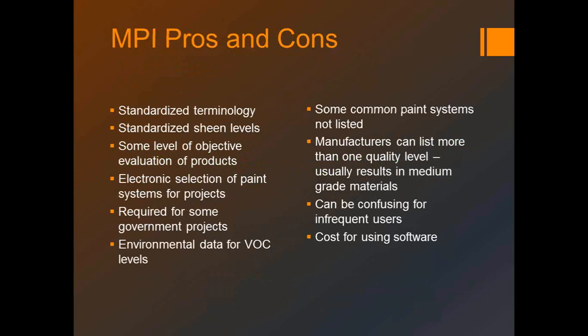Let me give you an example. If you're doing an apartment building where typically the interior walls of the units are painted with something that's not real expensive, we usually use the good line rather than the better or the best. Partly because the inhabitants are going to repaint. It's going to be repainted when they move out and somebody else comes in, and so there's just not a lot of point in putting in something that has a high scrubbability and good service life. So if you use the MPI system, you wouldn't need to name names. Just you'll get whatever is cost effective in that system.